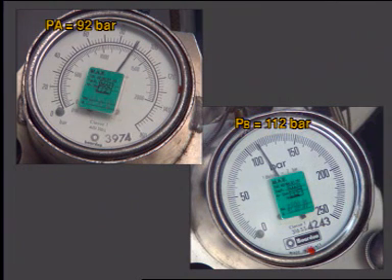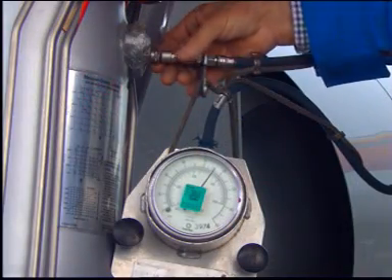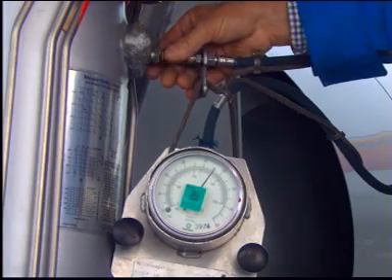Make sure that the difference in pressure at the top charging valve and the bottom charging valve is still more than 10.7 bar. Close the top and the bottom charging valves.